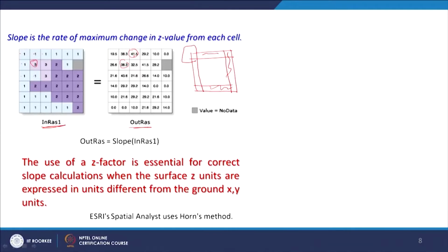So in the surrounding of this one, mainly on the northern side, the values might be much lower, and therefore this cell is getting a higher slope value. So for each cell that roving or moving window moves throughout your data set, throughout your matrix, and keeps calculating the slope value for the center cell, and this is how it is determined.